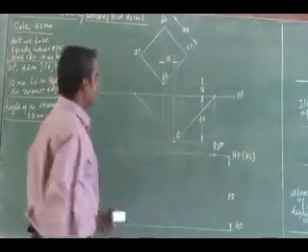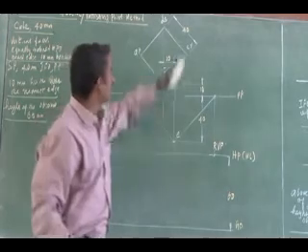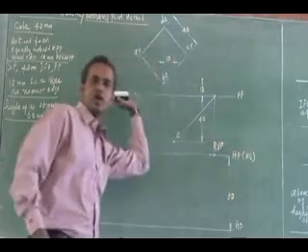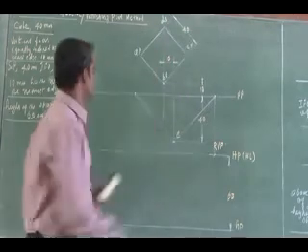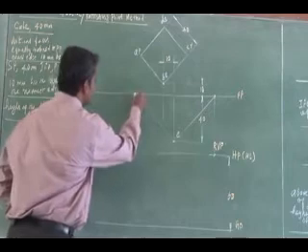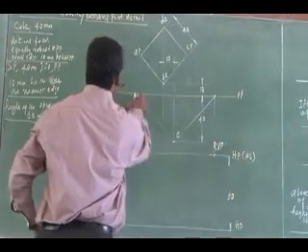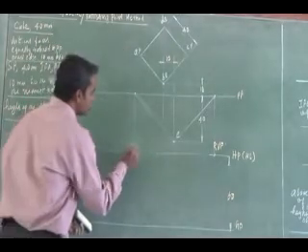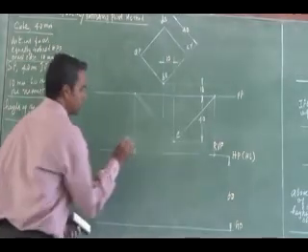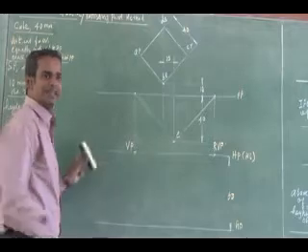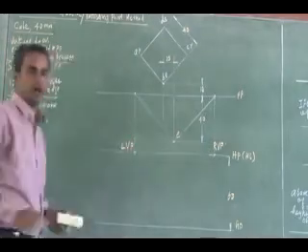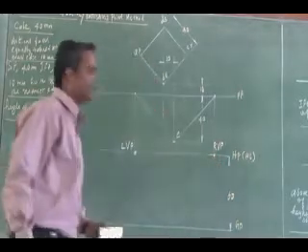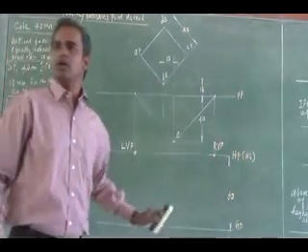Use your drafter fixed to this face and draw a parallel line. Then by dropping this, drawing a projector to the horizon line, this is going to be another vanishing point. What is this vanishing point? It is the left side, so the left vanishing point. So I have got two vanishing point locations, the right side and left side vanishing points. Is it clear?